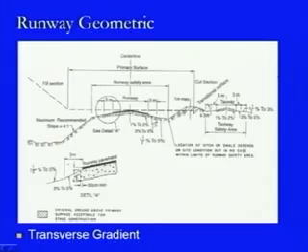And then we have the shoulder on this side, with a gradient of 3 to 5%, and after this shoulder we have 1.5 to 5% grade provided. So, these are the things being shown, and then this is the runway safety area from this point to this point, and this is the primary surface taken for the movement of any aircraft on this runway strip.